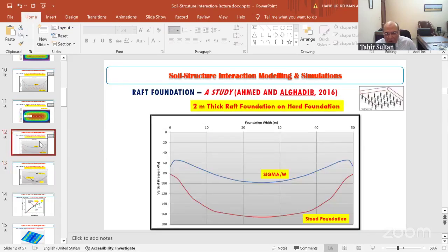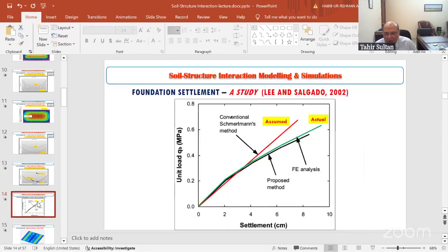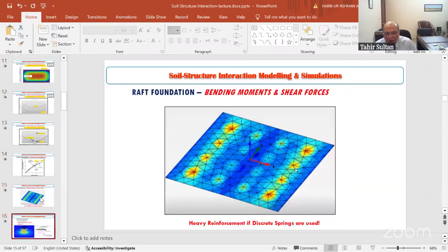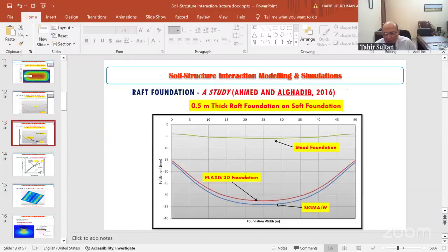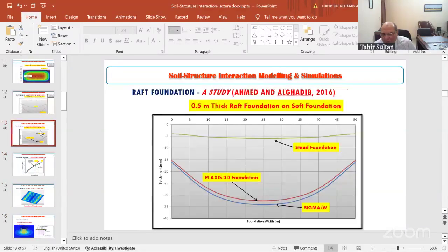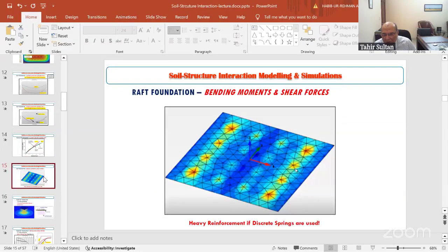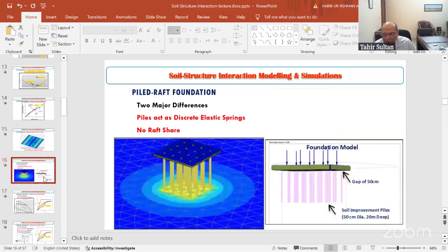The next question is from Rizwan Mirza, and he's asking: soil being known for its heterogeneity, can we realistically predict the actual deformations even when using relatively complex or sophisticated procedures? The reliability of results cannot hope to exceed the reliability of soil parameters adopted in the analysis. In addition, unless the adjoining structures are included in the model, the potential distress of them cannot be predicted. Is this not correct?